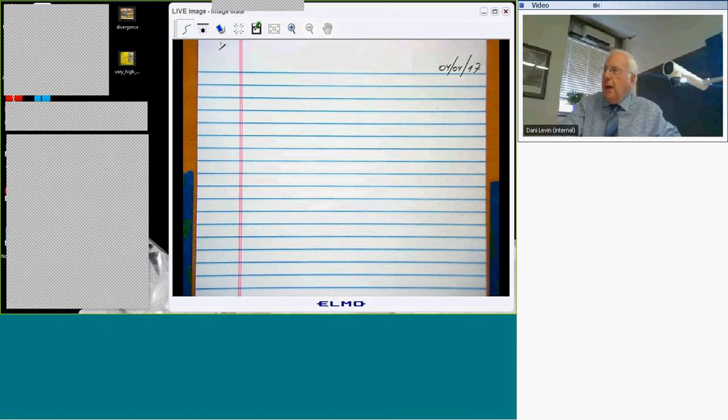I don't want to hold back your creativity, but I think the request was for an expansion in terms of inverse Mach number, and one reason why that expansion is useful is that it turns out to be an expansion in 1 over Mach number squared, right? Which means the series converges much faster as the Mach number increases. For Mach 5, 1 over Mach squared would be like 1 over 25, down at the noise level, which is smaller than the overall accuracy of the theory anyway.